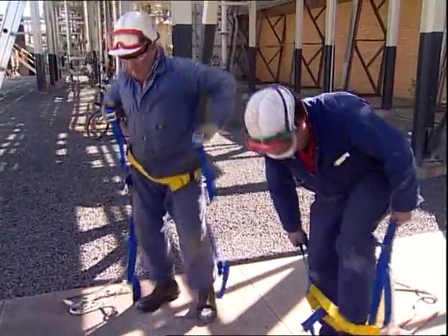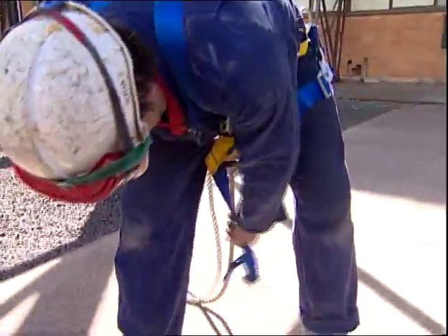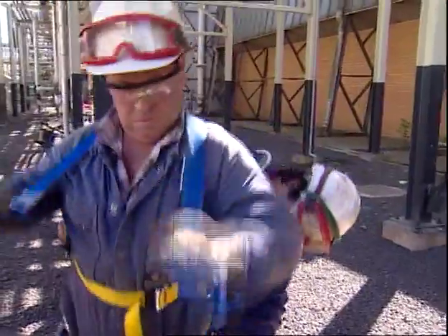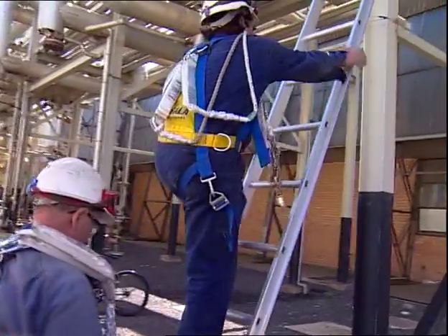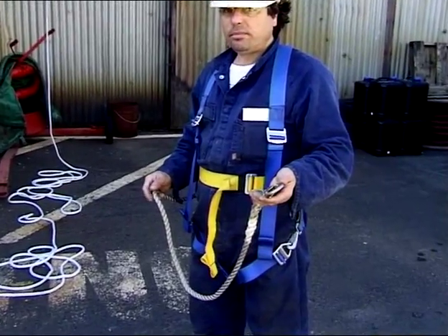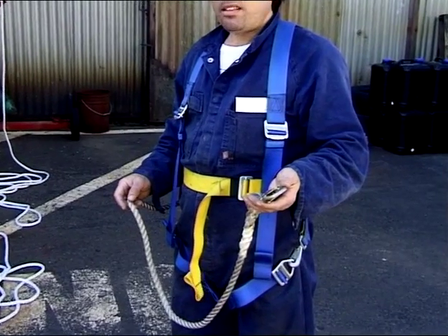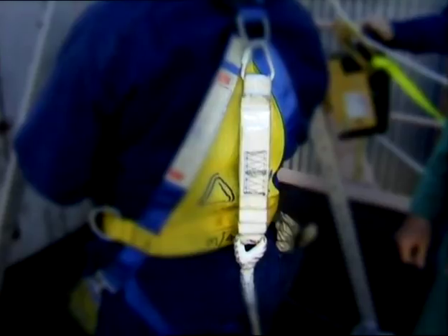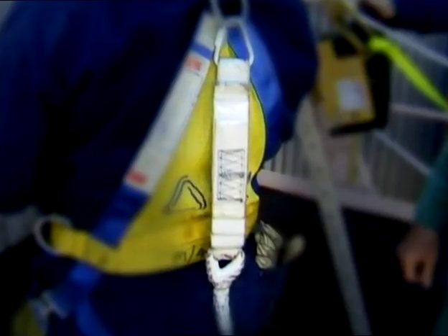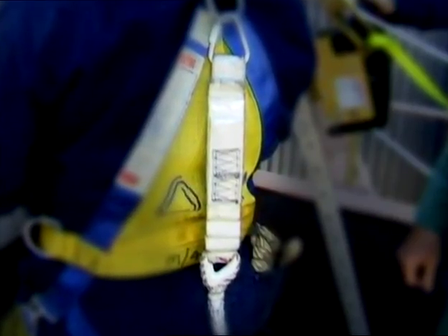A complete fall arrest system consists of a full body harness, a lanyard, a shock absorber, a fall arrestor, and a lifeline with secure anchorage points. A full body harness is designed to protect the person both during the fall and after the fall. The shock absorber is designed to absorb energy from a fall and results in less energy being transferred to the person, the lifeline, and anchor point. The shock absorber may be a separate device or it may be built into the lanyard design.